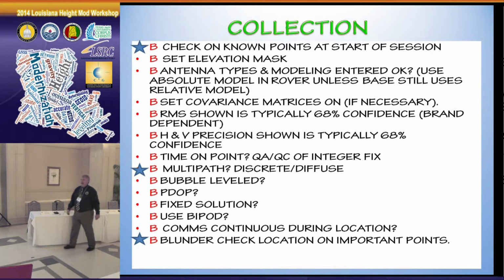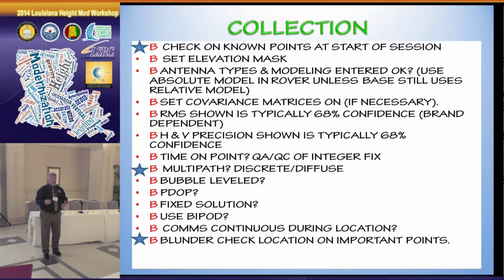If you're locating an important point, aside from redundancy, which we have to have on important points, and by redundancy I mean you come back to it later, not you dump your antenna and get another location on it. You want to blunder check that way though.